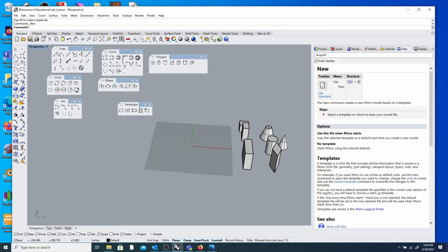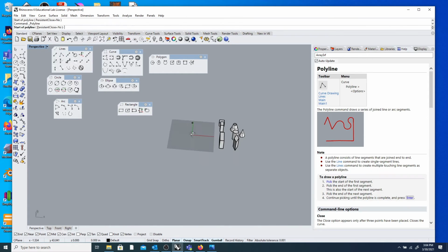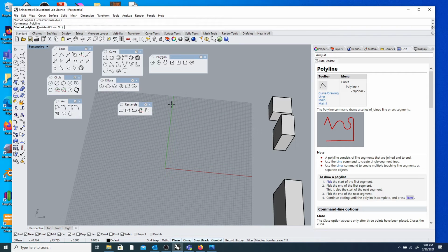So the most simple tool as far as the lines go is a single line, but typically you're choosing a polyline. If I click that, poly just means many, and it allows me to left click to start, and then you can see up at the command line, it's telling me I want the next point.